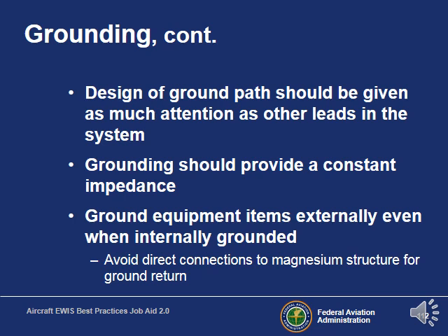All components need to be externally grounded. Even if they have an internal ground, all the components also need to be connected externally to the airframe.